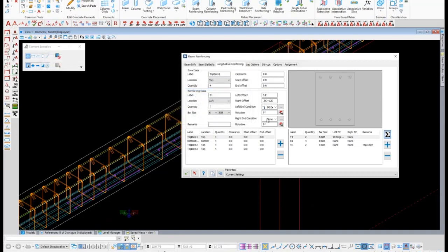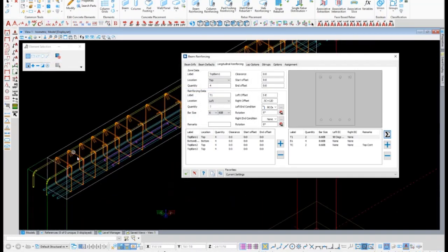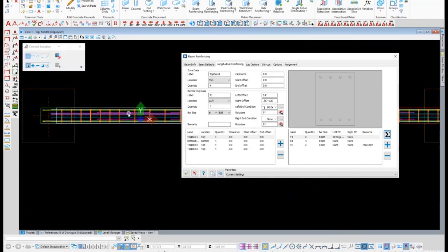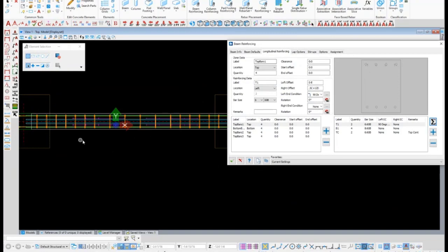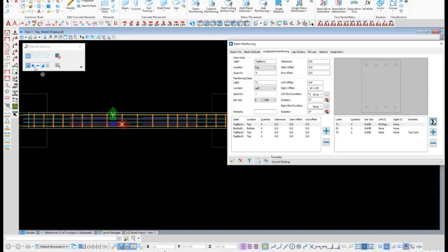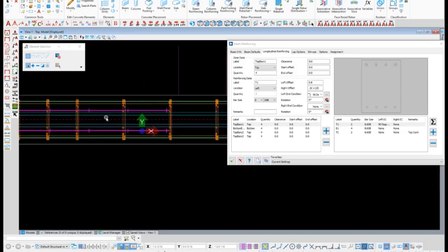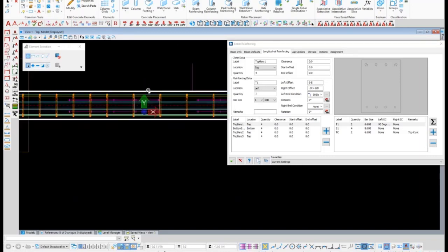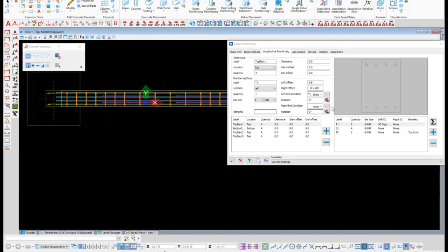But what we're going to look at now is, whenever we're inside of a beam, prior to this enhancement, all we would see is the links. A user would have to come through, and when they're looking at reinforcing a beam, they may have to figure out where the center span of that beam is, maybe make some lines, figure out what my lap length may be, and offset some lines. It's very tedious, whereas now, through the actual beam macros, you can see and build your beam as needed.